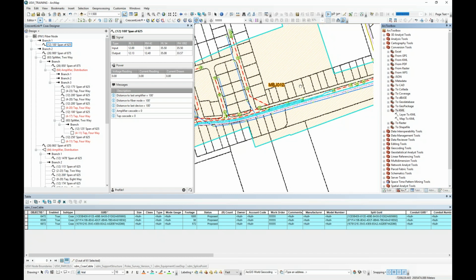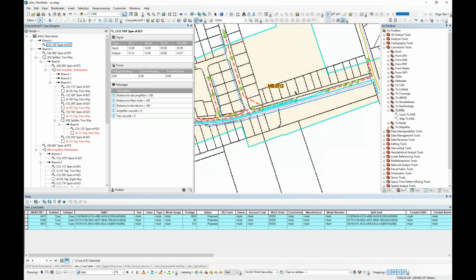Let me show one of the tools that we use a lot to output maps for other people to utilize. Just quick maps that we can do. Outputting some of these facilities to a KMZ or a KML, you can use in Google Earth. That's what we use a lot. So based on a selection, this is part of the Coax that was created. You can go to the Arc toolbox, which is in this palette on the right, or you can go to Geoprocessing, Arc toolbox.